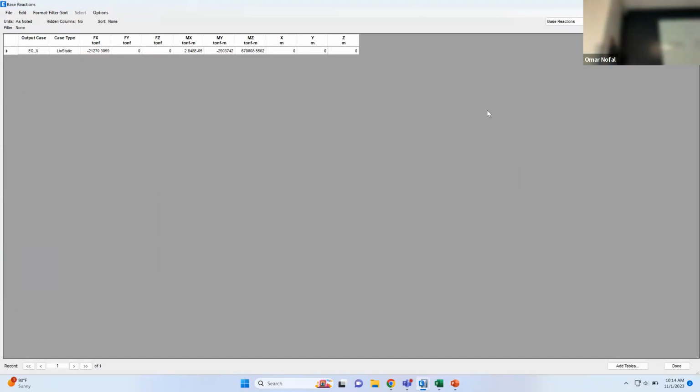This is the amount of base shear. That's the value that I told you, the most important value when we talk about earthquake. When I say earthquake, the first thing that comes to your mind is base shear and response spectrum, because this is how you are going to solve your model. What is the value of the base shear on the building that this earthquake generated?